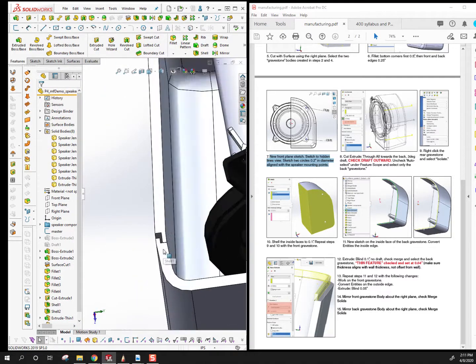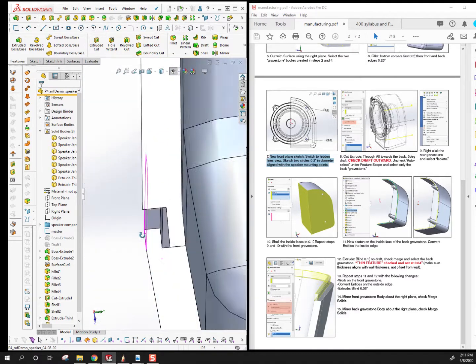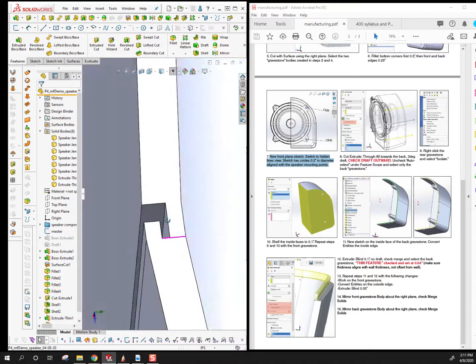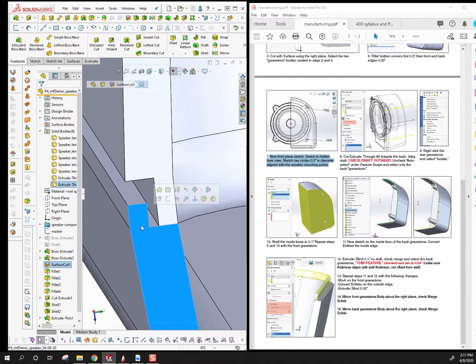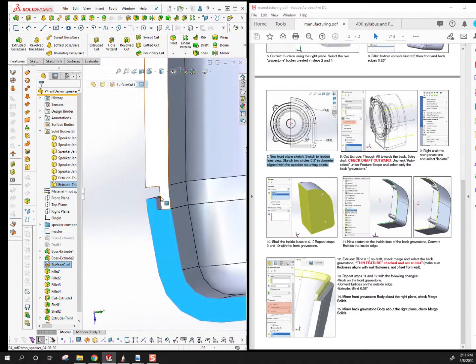If you have ever taken apart an object or looked at it carefully, most part lines are designed this way. Okay, so this is a bit of a deep dive. This is a little bit of materials and methods, or materials and manufacturing, in this class. Part lines are designed this way for a couple reasons. One, the reason why one goes to the inside and one goes to the outside is that this way it's kind of a secure puzzle connection.